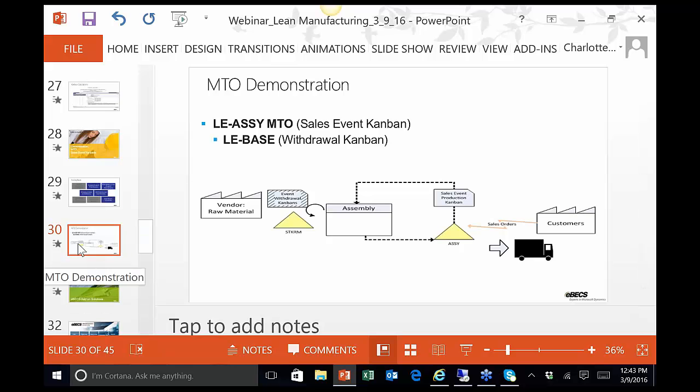All right. That was our make-to-order scenario. Again, sales order drives production on the assembly cell and pull to order. So we only pull the materials that we need to the assembly cell. Again, that runners, repeaters, strangers model, and going back to those Kanban replenishment strategies, I've seen a lot of times where, if you've got strangers sitting at the line side, it doesn't make sense. You might not have space, you might not have room, so you would put those in the raw material warehouse and pull them only when you need them, even if this is a make-to-stock scenario. So it's really mix and match. It's really building blocks.